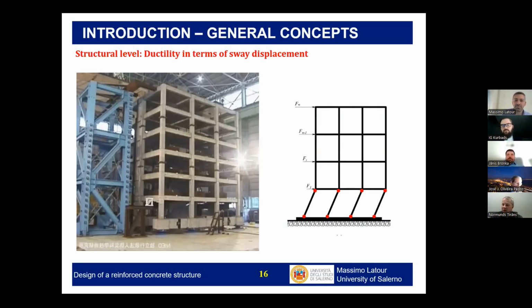And this is the answer to the last question. Explain why flat slabs are not advised in seismic regions. This is the same as what was explained in our lecture, that the column is weaker. The problem is that with the flat slab, you have a very rigid, strong floor, and then the failure will probably be in the column.